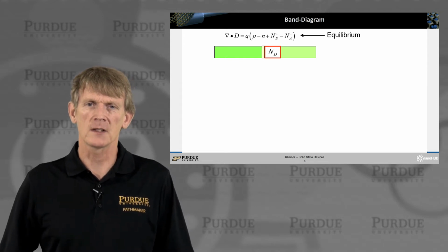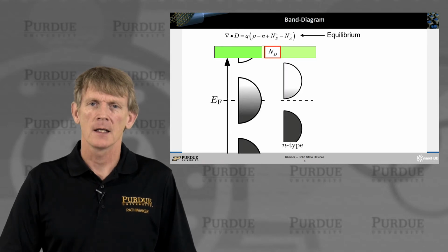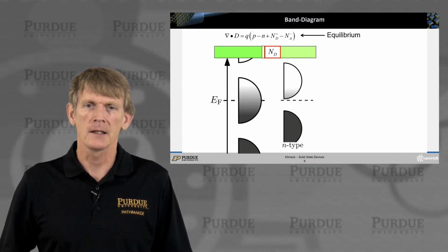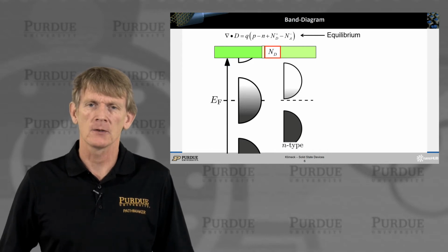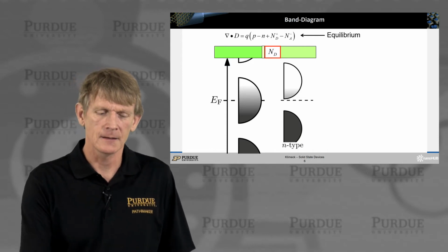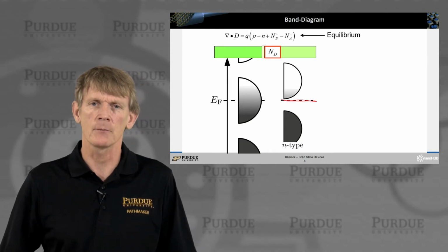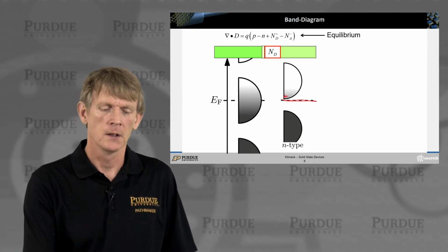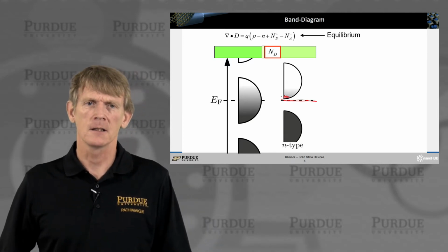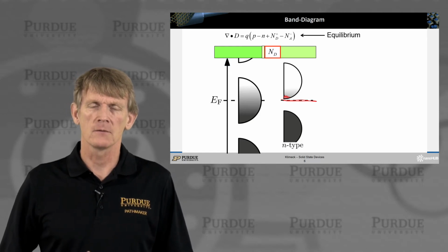All right, so we'll start with a band edge diagram, of course, in equilibrium. And I just want to remind you that a metal and a semiconductor are somewhat different. In the N-type doped semiconductor, we have the Fermi level close to the conduction band edge, and we manage somehow to populate a few states here in the conduction band, versus a metal really has a Fermi level roughly through the middle of a band.